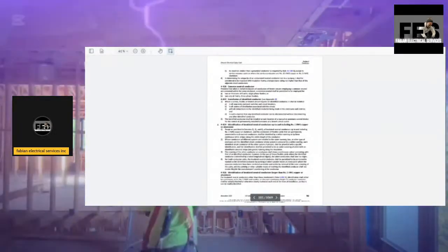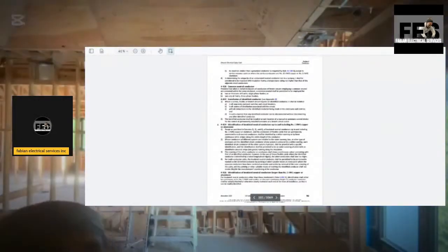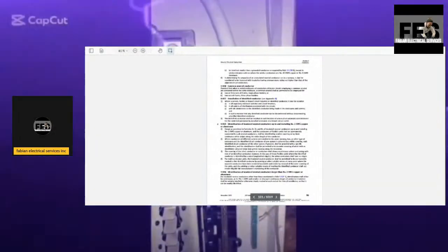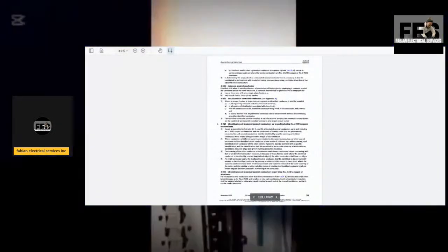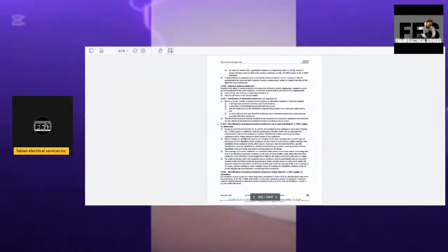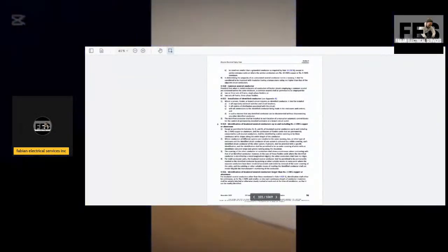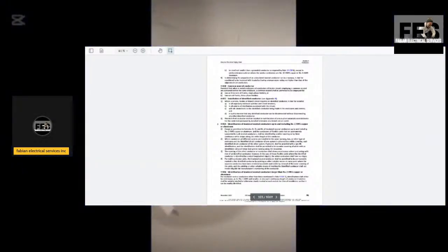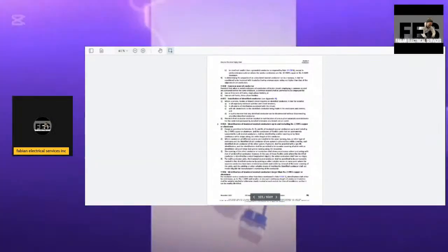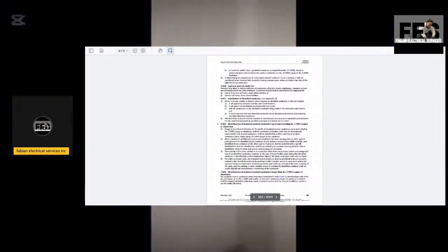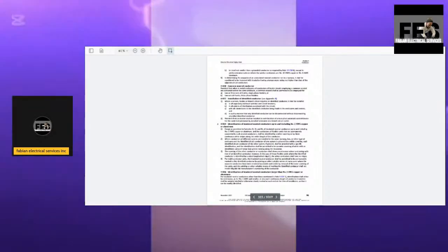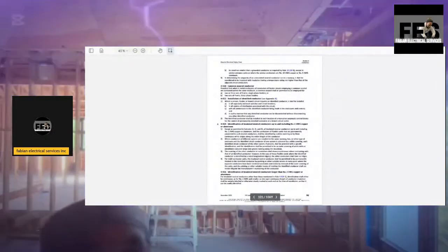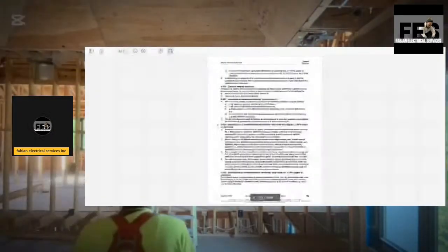That means you're going to change up the tape that you use, in different colors. You're not going to make them all the same colors, or you're going to end up mixing up circuits. The covering of the other conductor or conductors shall show a continuous color contrasting with that of an identified conductor.